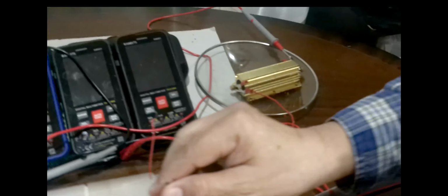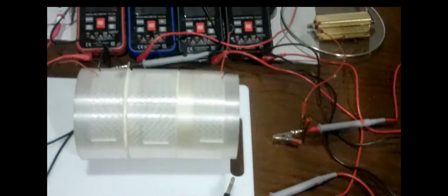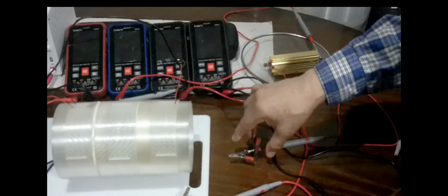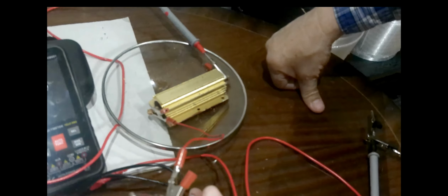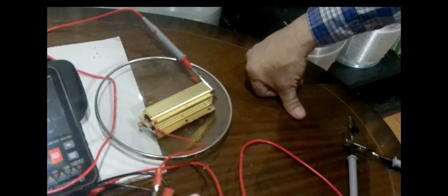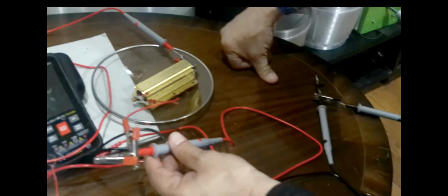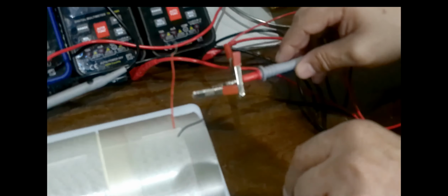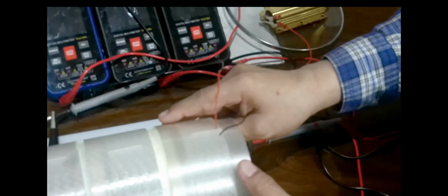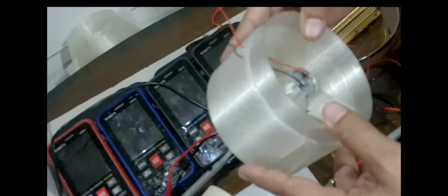And in order to find the output power, the energy, the electricity, we attach an electric load, an electric resistor like this one. For this demonstration, we're going to use a 200 watts, 8 ohms resistor, and we attach it to the positive and negative leads of the turbine. In this case we don't call it DC motor, we call it dynamo or DC generator.